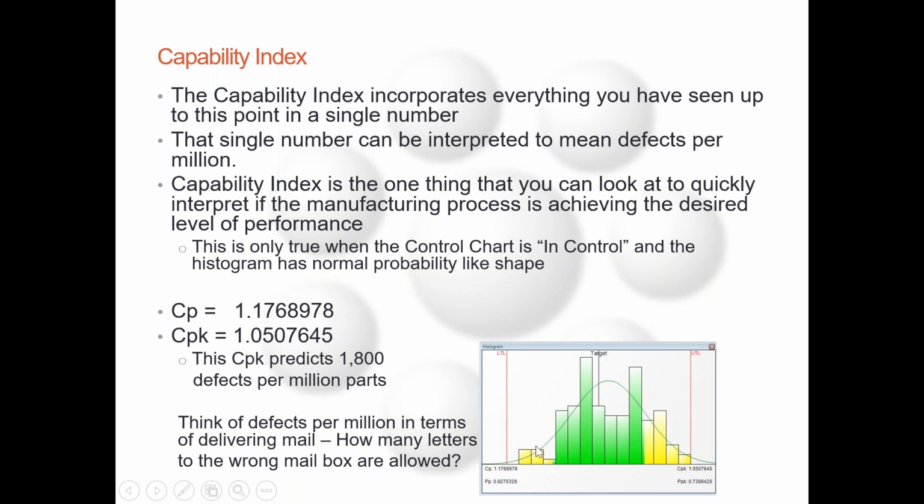And I'm coming back for this particular data, which we'll see a little bit more about. And here is the curve. The curve is pretty well centered on where the data is, but it tells us while we have a 1.18 CPK, how tight it is this way, once we account for the fact that it has drifted away from the center, we only have a 1.05 CPK. So it's CP and CPK. This predicts that we'd have 1,800 defects per million. So you're starting to see that CPK, in summarizing what's going on, is also telling us how much to expect in the case of bad parts in a lot.